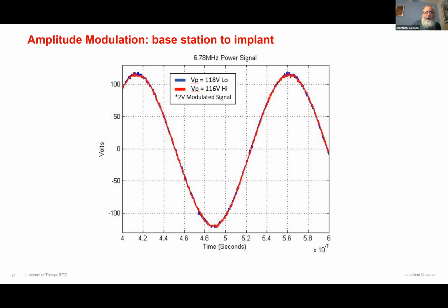Oh, I didn't show you the circuit. We started with, okay, so how do you make a sine wave? How do you make a sine wave? A DAC? Okay, that's one way to do it. You've got to make it at 6 megahertz, right? So if you go your 319K route, you've got a very fast DAC to make a sine wave at 6 megahertz.